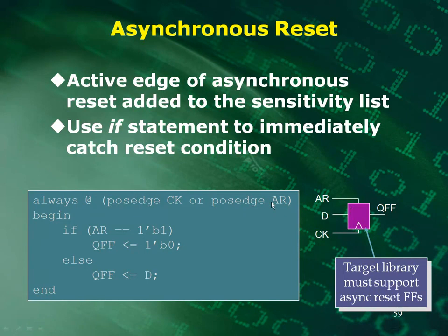You can violate setup and holds. Maybe I should post a good paper that somebody wrote on this. What can happen is when you release the asynchronous reset with respect to the clock, you can violate hold conditions, and that would produce problems on your output. I probably need to put up a paper for you to read about that.